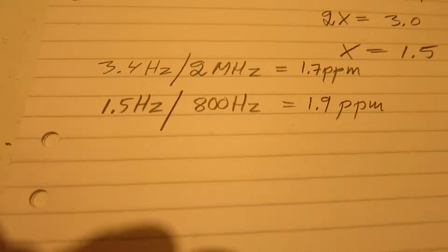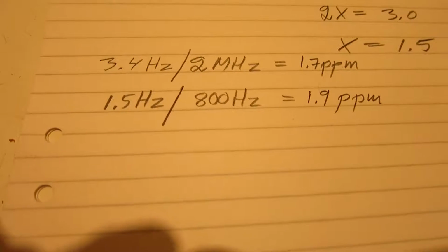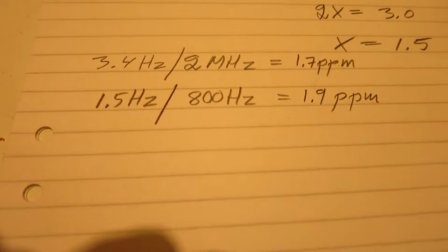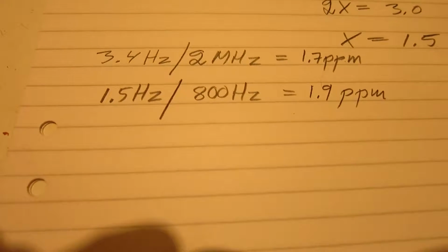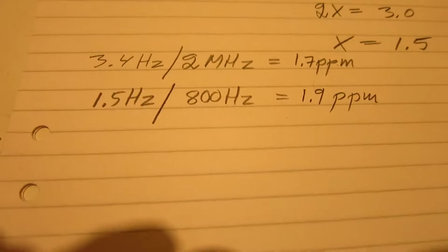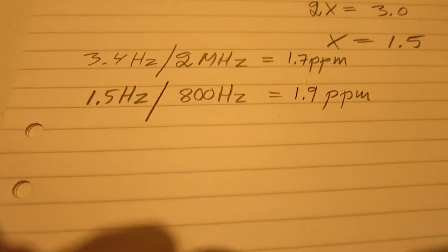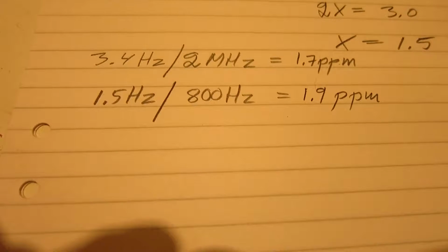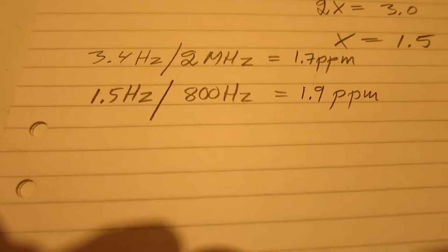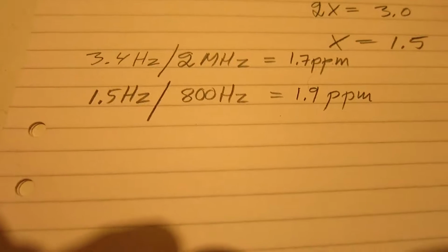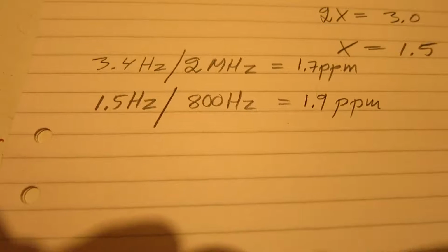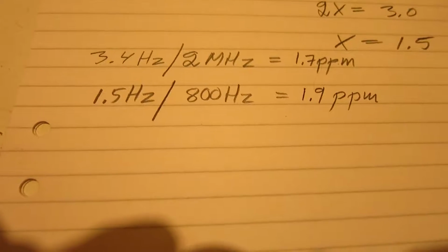This is something I don't know for sure, so I will now modify Linrad to accommodate two more parameters when playing recorded files. One is to set the error on the center frequency, and the other is to set the error on the baseband sampling speed, the rate that Linrad receives from the hardware.